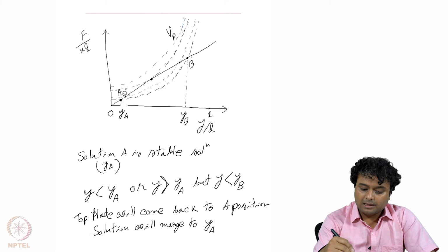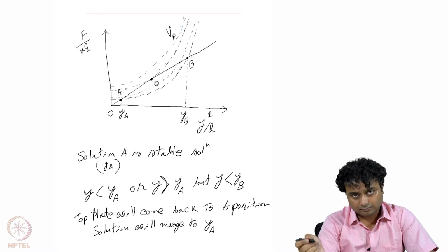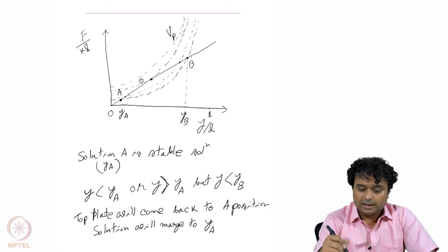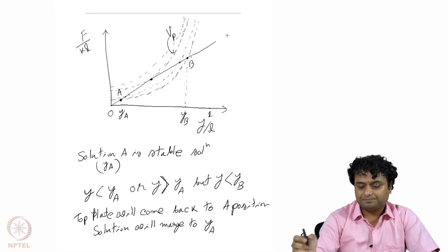Also we have seen that these different lines are for different voltages, and at some voltage where the electrostatic force just touches the mechanical force, this is called the pull in voltage. Above that, electrostatic attraction is always higher than the mechanical force, so there is no chance that the beam can be pulled back again. So this is called pull in voltage, Vp, and this is the graph for Vp where it is exactly touching the mechanical force.